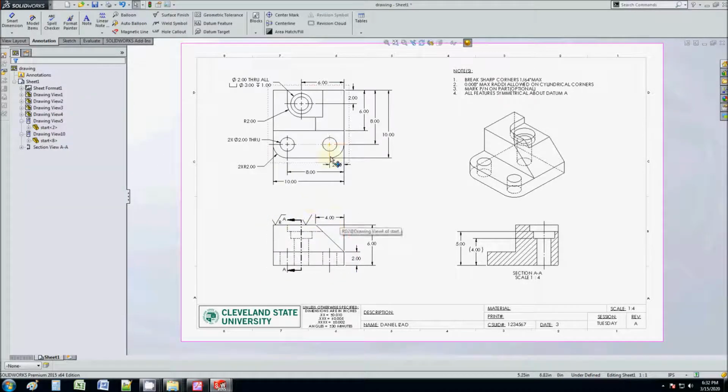The only times in my experience that I've had to spec surface finish symbols, one was in bearing design. With bearings, a lot of times when you want to maintain a certain lubrication thickness between the housing and the rollers, sometimes you have to polish the surfaces, otherwise the rollers will contact and create heat and wear out your bearings. So to maintain that minimum film thickness, sometimes you have to specify special lapping surface finishes to achieve that.